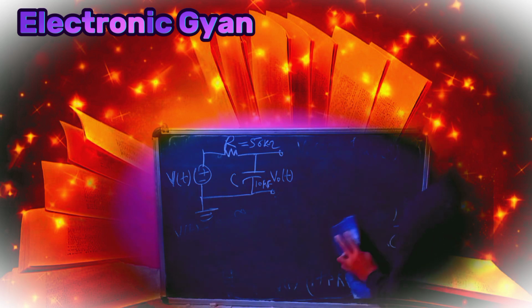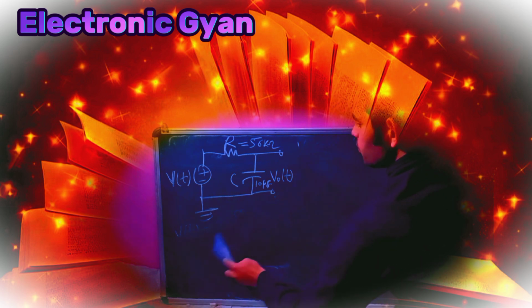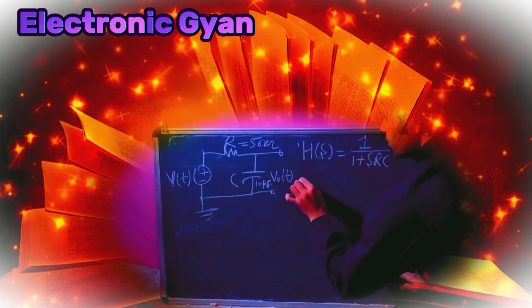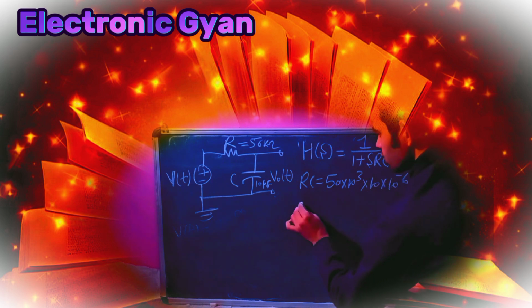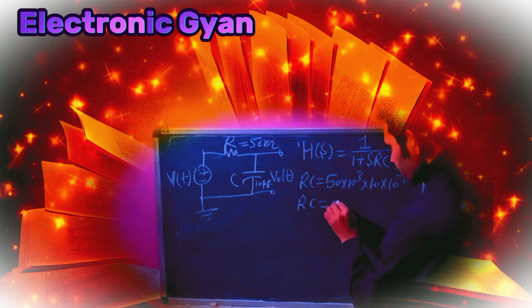We got the transfer function as 1 by 1 plus sRC, where R is 50 into 10 to the power 3, and C is 10 microfarad, 10 to the power minus 6. So my RC will be 0.5.